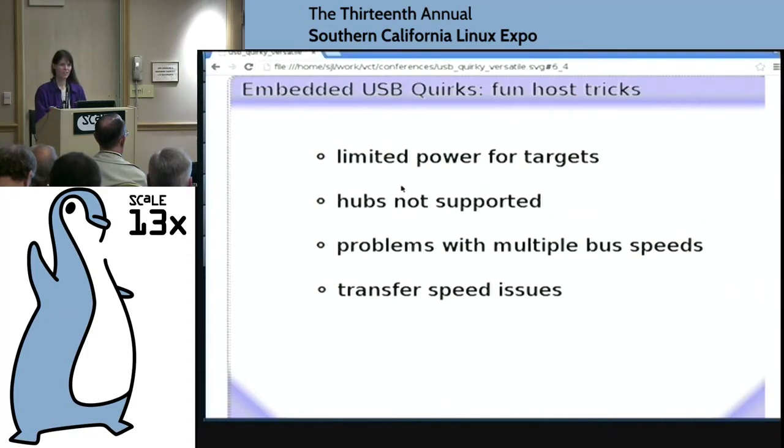I don't think you're ever going to see this on, say, that Minnow board Max that we were hearing about this morning. But especially as you go towards the low power side rather than the CPU horsepower side, you can have this transfer speed problem. Also, the really, really cheap can get in here too, because even if you have low power, a good DMA controller can save you. But suppose you don't have a decent DMA controller, or suppose the vendor gave you a cruddy driver that maybe doesn't even enable DMA, then you're really hosed trying to do PIO USB on a USB 2 speed stream.